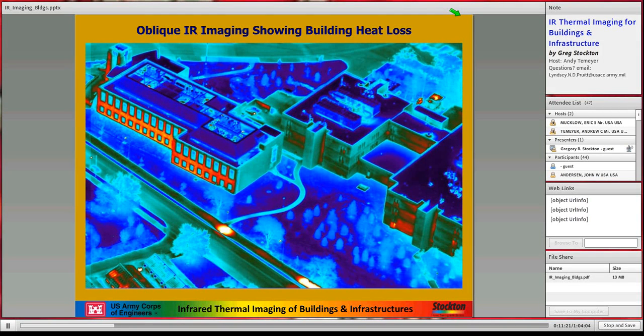The key here, and this is super duper important for everything, is that when you're looking at quality of something, we're with infrared thermography looking at surface temperatures. Surface temperatures. We don't see inside buildings. We see the impact from whatever's going on in the building, and the quality of the surface on the outside should be homogeneous. Where we don't see a homogeneous surface, we know something else is going on. So I'll come back to this in a minute when we start looking at other things, but the point being that